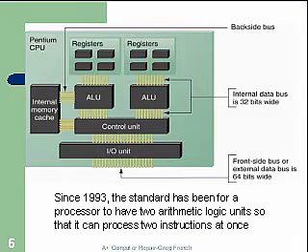Here's a diagram of a CPU on the left-hand side here. You can see here's this memory cache, and connected to it is what we call the backside bus. We have two sets of registers, two sets of ALUs, and the internal data bus size is 32 bits on this particular processor. Today we see mostly 64. Then the front side bus, which connects us to the rest of the computer, is located right here. Front side bus has been 64 bits wide for quite a long time.